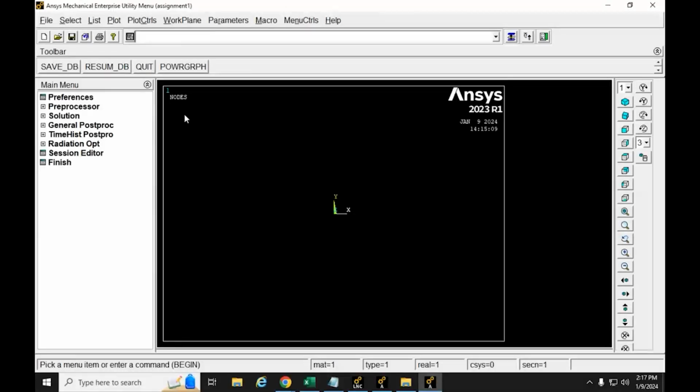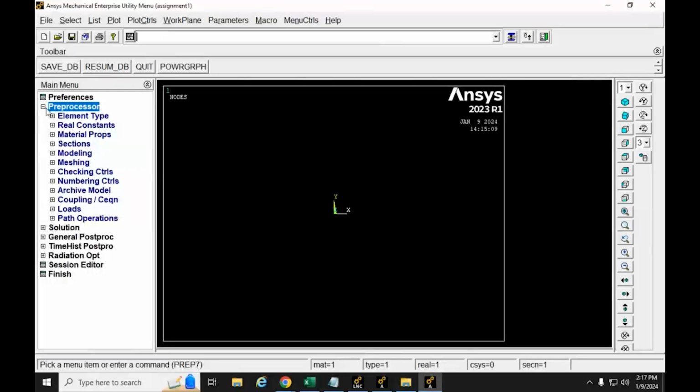So, this software allows us to do some very simple things like a rigid plate spring system, and allows us to understand the finite element approach from very simple elements. When we get into Workbench, it's mainly the brick element, which is an 8-noded, or actually uses a 20-noded element, which has mid-nodes on the side of the element.